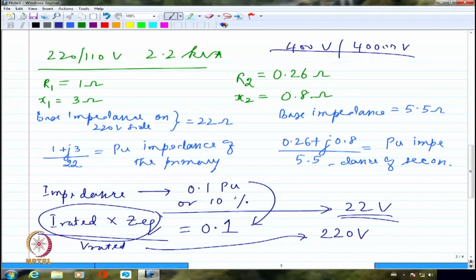Whereas, if I look at an induction motor, I can say normally the series impedances will add up to 25 to 30%. So, roughly we have the ranges for different machines. So, by just observing, we would be able to say whether the values are falling within the range. That's the first advantage.